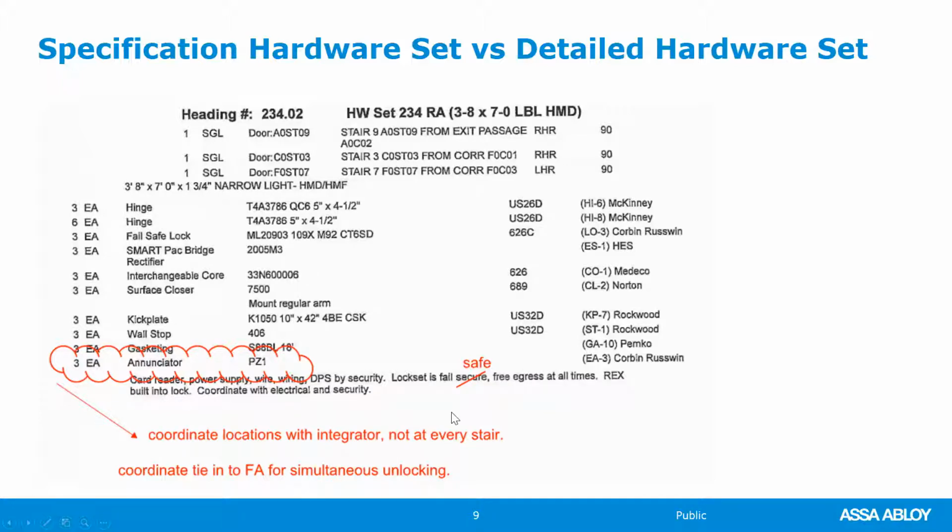Now, I just want to make sure to point out that the Door and Hardware Institute, we will follow, and we do follow, DHI's format: hang the door, secure the door, control the door, protect the door. We follow that format, but a specification hardware set does not go into the same amount of detail as a DHI for your certification. The hardware applications and selecting hardware and the thought process behind it will help you if you are wanting to take your DHI credentials and go through that process.